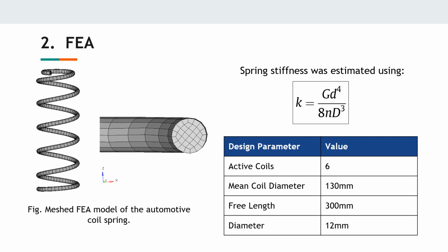Natural frequency of the suspension system should be within a range of 1 to 1.5 Hz in order to ensure optimum ride comfort for passenger cars. The spring stiffness range for the sensitivity analysis was chosen based on this range of natural frequencies.